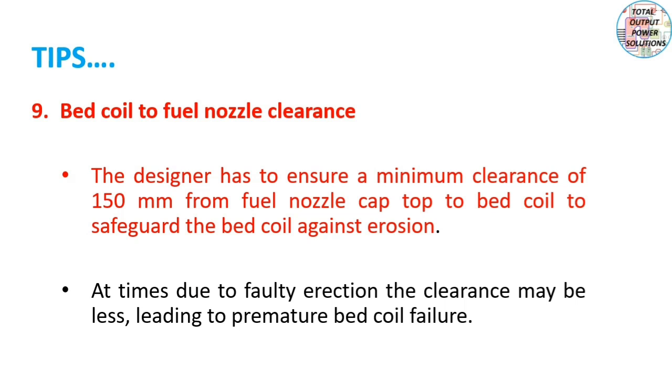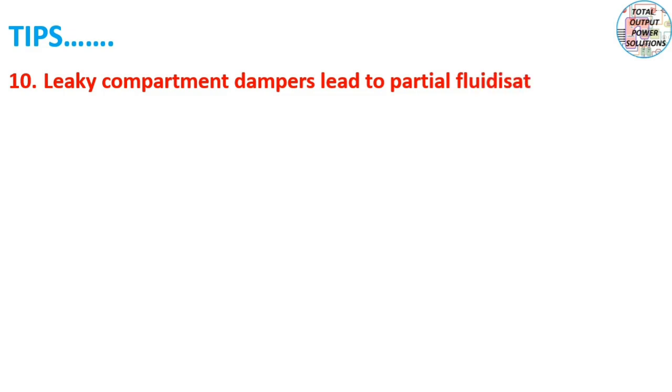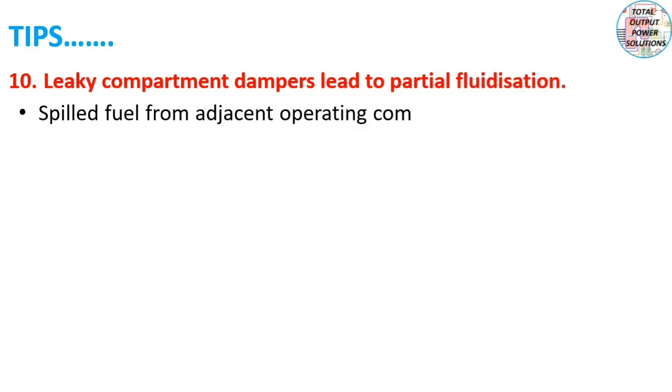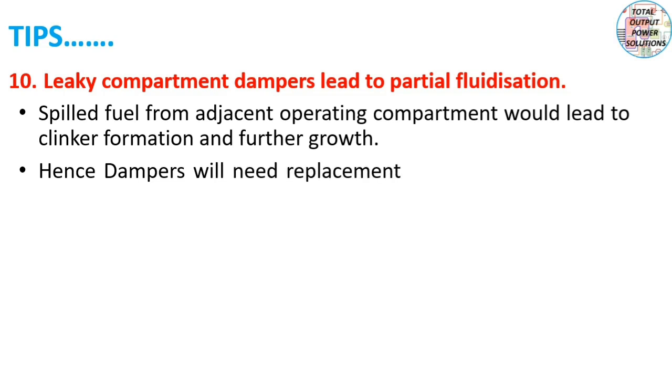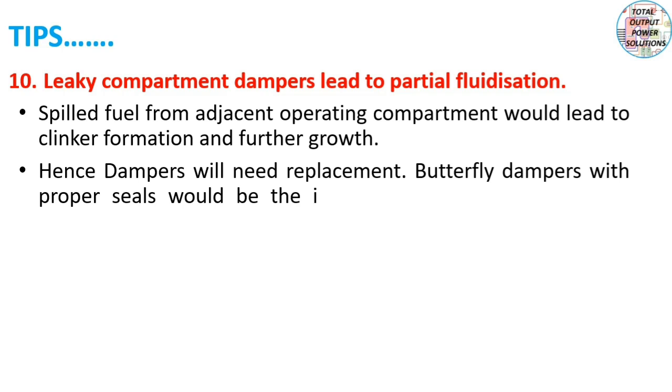Tip number 10. Leaky compartment dampers lead to partial fluidization. Spilled fuel from the adjacent operating compartment would lead to clinker formation and further growth of the clinker. Hence, dampers will need replacement. Butterfly dampers with proper seals would be the ideal choice to solve the clinker problem.